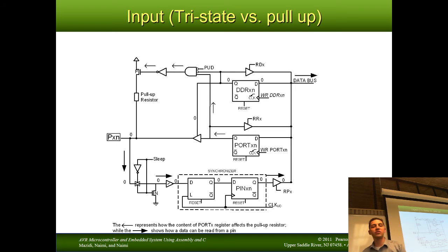The one thing that you have to be concerned about occasionally is if you write to a port and then try to read in from a port one instruction after it, you're going to get the value that was on that pin 1 cycle ago because of this 2-bit shift register. So if I outputted a 1 and then read immediately from that same bit, I would not see that 1. Okay? I would have to wait 1 more cycle.